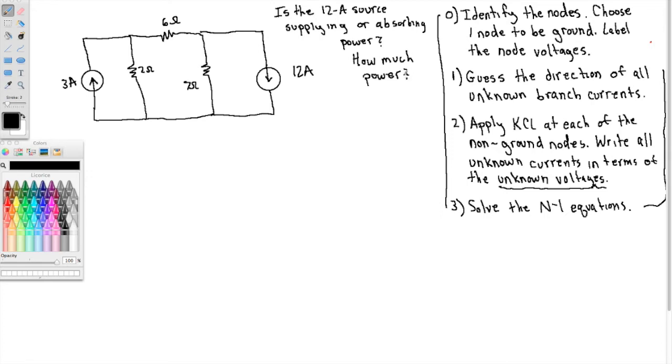All right. Well, our tools to use, first our Ohm's law. But again, this 3 amps comes in and you don't know how it splits. 12 amps comes down here, you don't know how it splits. So you don't know the current through any of those resistors. You can't use Ohm's law. Kirchhoff's law is our next line of defense. Well, we don't just have one loop here, we've got several. And we don't just have 2 nodes, we don't just have a parallel circuit, so we don't want to use Kirchhoff's current law either, not directly anyway.